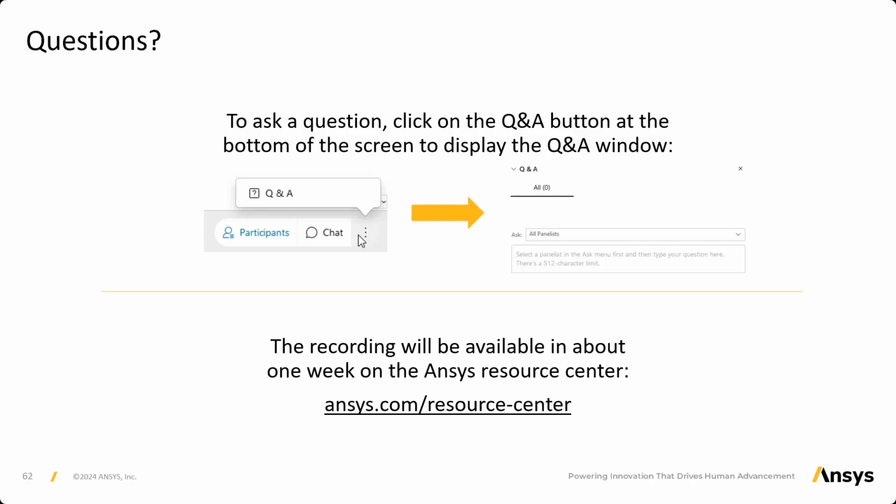Okay. Final question regarding the creation of camera sensor in Speos. The origin of the camera sensor basically corresponds to the image location, not the lens itself. So you need to account also for the size of the lens system. So basically, if you put an object too close to the camera sensor, you might have some issues.